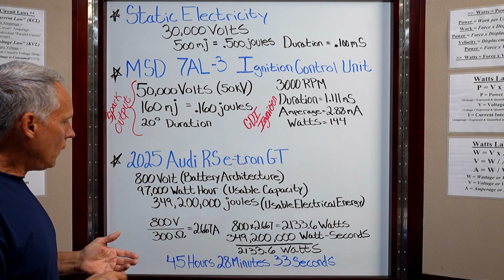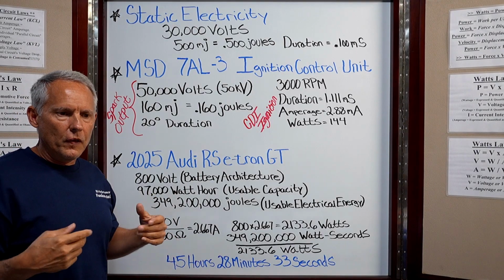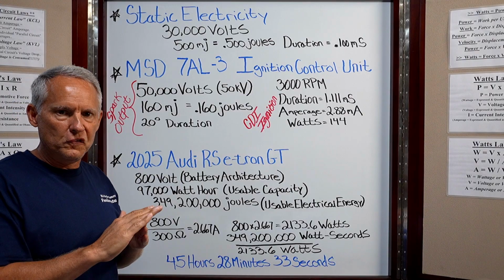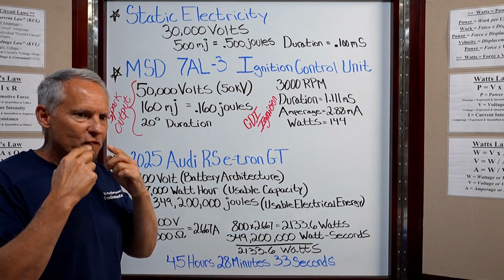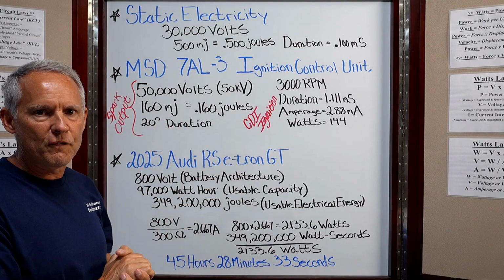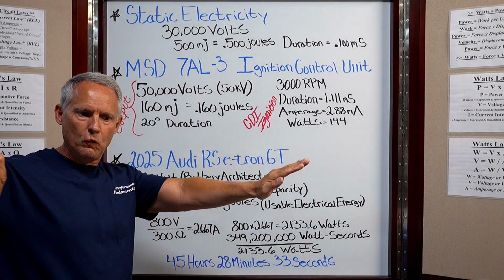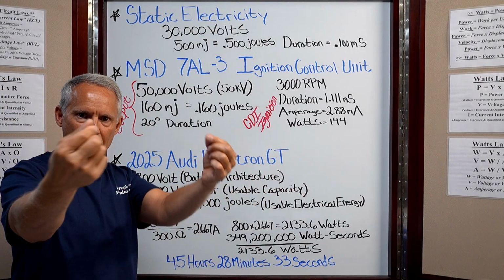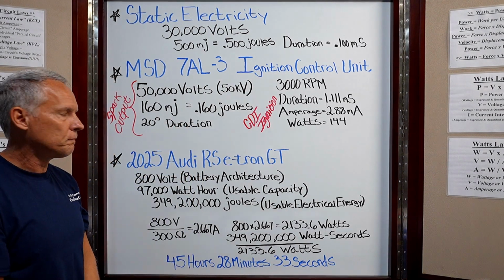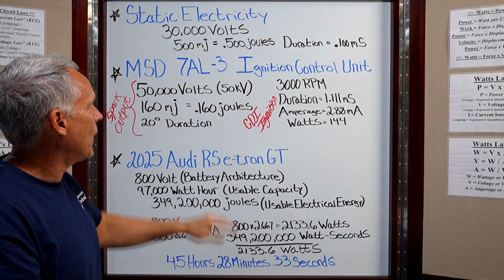Okay, so let's take a look at something real quick. Let's do a real quick calculation. The skin of the human body is not very conductive, it has a lot of resistance. I checked mine the other day. I licked my fingers and stuck my ohm meter probes between my fingers. I had about 55,000 ohms. That's a lot of resistance. That's through my skin, from one path, whatever path it took to get from here to back to here. It was calculated at 55,000 ohms. That's a lot of resistance, and that helps in situations like this to protect you from real quick zaps like that.